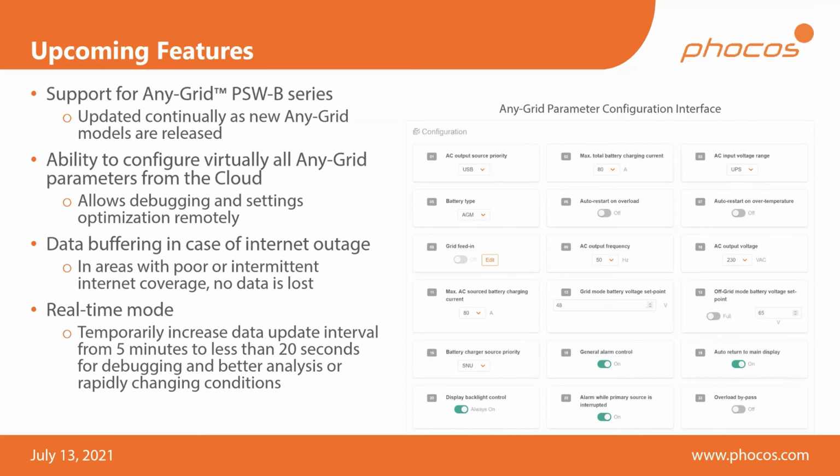The AB-PLC is designed in such a way that we have a significant amount of storage on board. What that means is if the internet connection drops and if the internet is not available, then the AB-PLC will keep querying the connected power devices, will build its averages, and instead of sending that data to the cloud, it will save the data locally on the internal memory. And then as soon as the internet connection comes back, it will then progressively update the cloud portal with the data that it has previously stored locally. And this way you will end up with a seamless amount of data, and you won't have any holes in your data, even if you have intermittent internet outages.